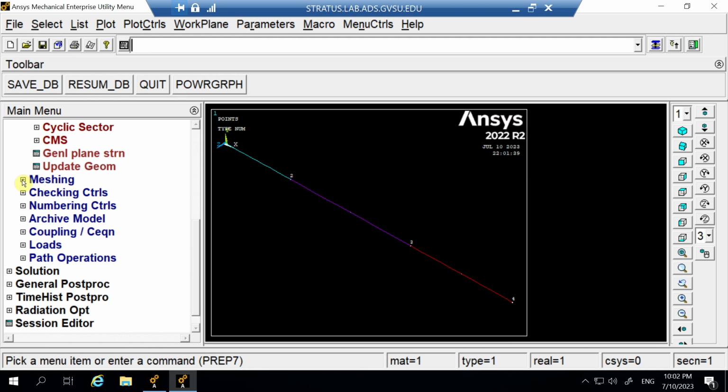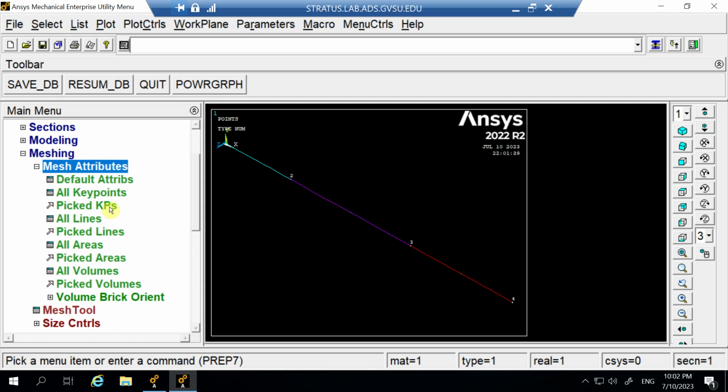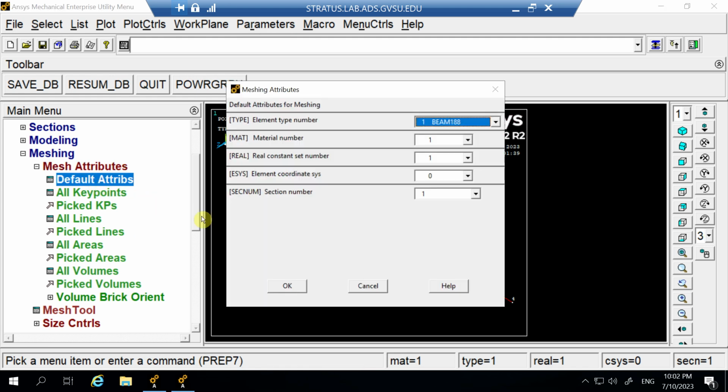Now for meshing, okay. So if you remember, we have to assign attributes, the properties of the sections we have defined. The shaft has a diameter of 1 inch, so we have to indicate that to ANSYS. And then those key points that we have gears sitting on, we have to assign those gears to those points that I have here. Alright, so let's go here.